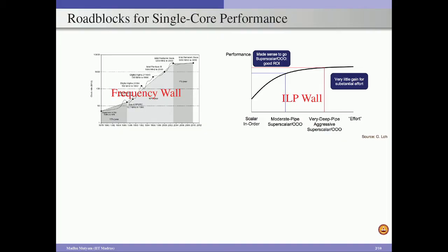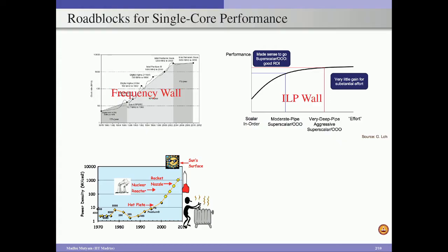And the third driving force for us to go from single core to multi-core is the power density. As I mentioned earlier, power per unit area is called power density. Once we have more and more transistors integrated on a single chip, and the area of the chip is very small, and we are clocking all the available transistors with high clock frequency, these transistors are going to consume power, and the overall power density is going to increase significantly.